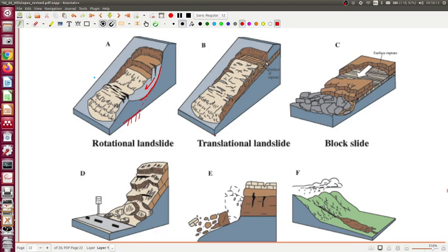Of course, there can be other cases in which the hill slope is looking like this, where it has a steeper slope than the landslide scarp itself, then we can have a rupture here, which then daylights at the surface right there. And so that creates a simple planar failure, and that is a translational landslide.